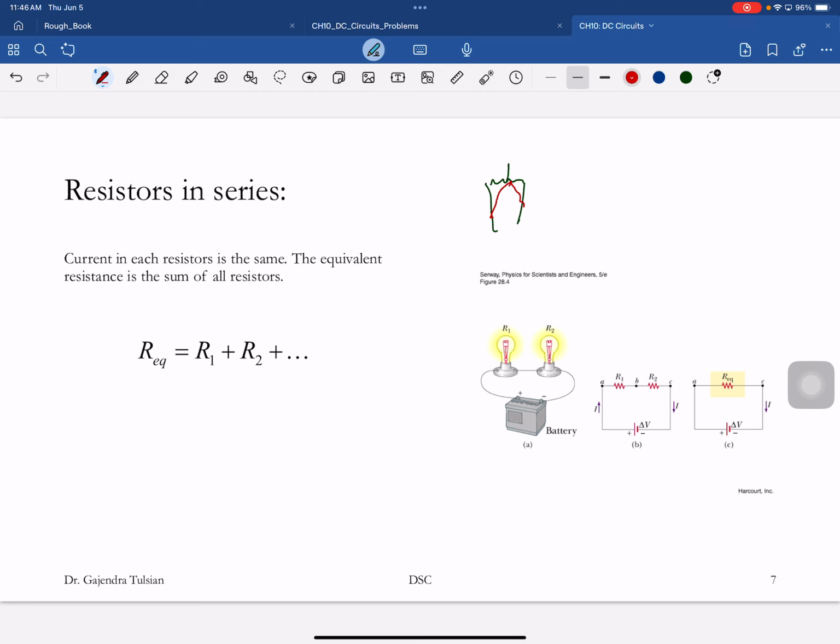If you put them in parallel, you would use a lot of wiring for stringing. All those wires have to come to the plug. A series connection uses a lot less wire. So if this were 100 bulbs with a parallel connection, you would need a wire 100 times the length of the series connection.